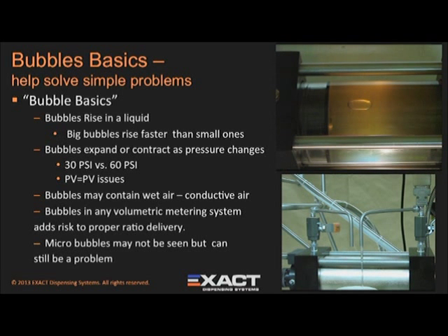Bubbles under pressure get smaller, but they do not disappear. See the video as the pressure goes from 30 psi to 60 psi. The bubble changes size. It is very important, no matter whose meter mix equipment you are using, to get the air out of the system. We use a simple bleed process that's pictured here in the second video on this slide.